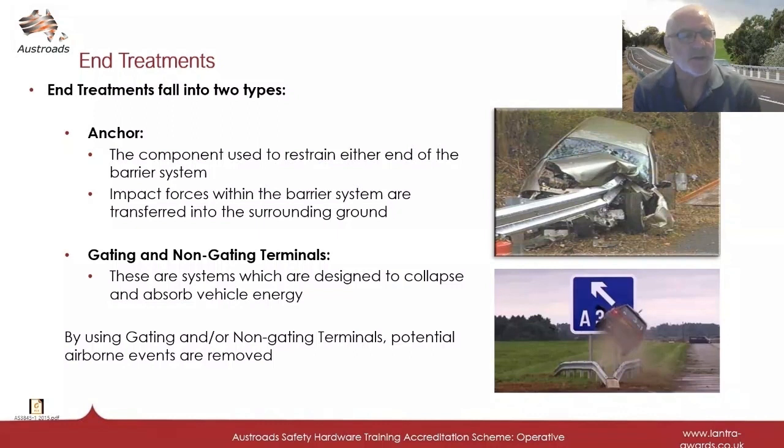For approach protection, gating or non-gating terminals are to be installed. These systems are designed to collapse and absorb vehicle energy. By using gating and/or non-gating terminals, potential airborne events are removed.